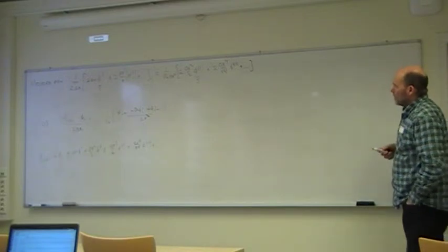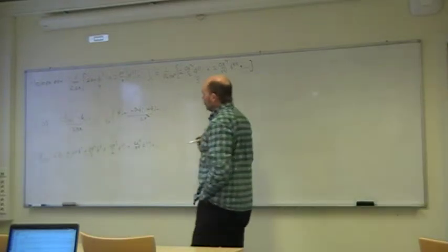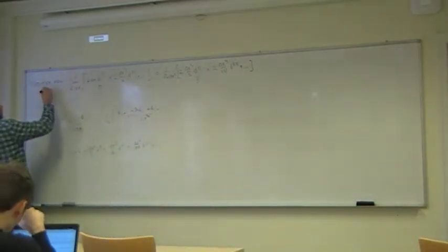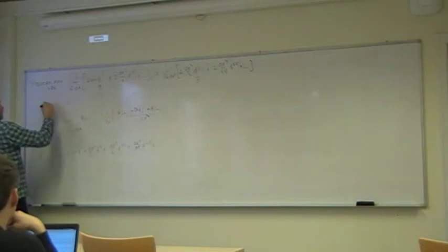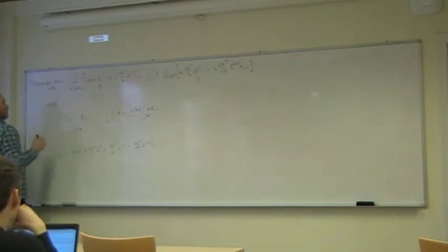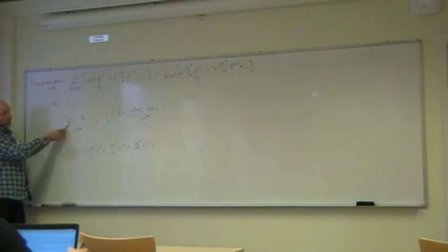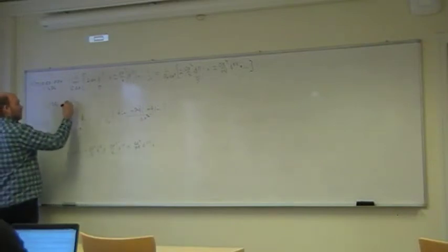What will now be the difference if I jump to the UDS? This was a CDS, and now UDS. It's a little narrow, but it shouldn't be too hard. The only difference is then the first term here. No plus 1 and no 2 here. So I will have 1 over a single delta x.